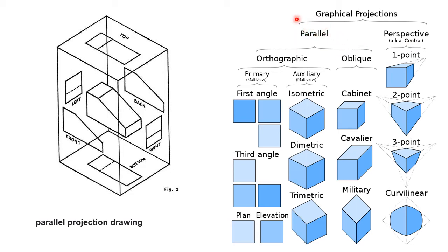A parallel projection drawing is a projection of an object in three-dimensional space onto a fixed plane known as the projection plane or image plane, where the rays, known as the lines of sight or projection lines, are parallel to each other. It is a basic tool in descriptive geometry. The projection is called orthographic if the rays are perpendicular or orthogonal to the image plane, and oblique or skew if they are not.